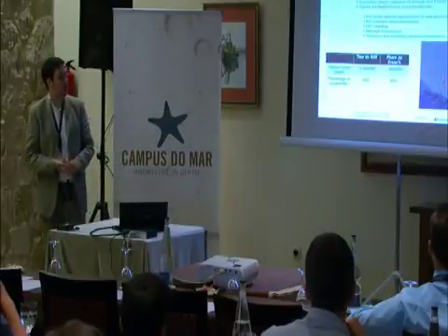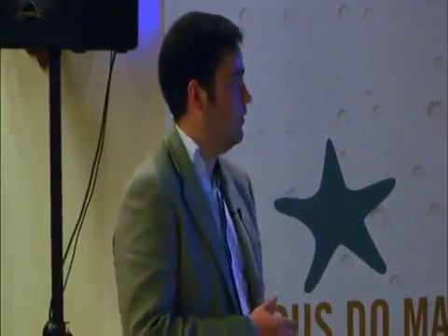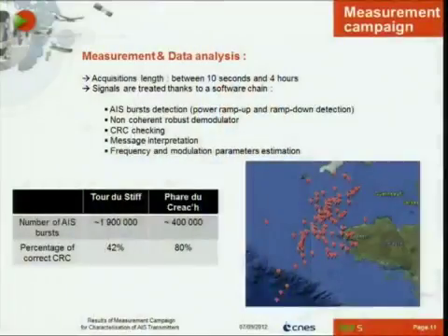During this week, several acquisitions have been done. Length of these acquisitions is between 10 seconds and 4 hours. Then received signals are treated thanks to a software chain that contains AIS burst detection, demodulation thanks to a non-coherent robust demodulator, CRC checking, message interpretation, and frequency and modulation parameter estimation.